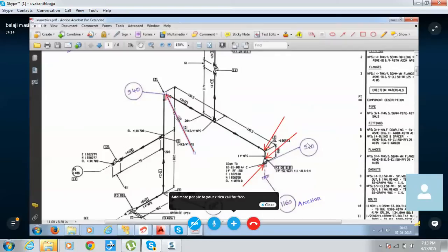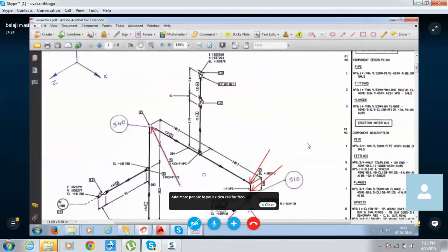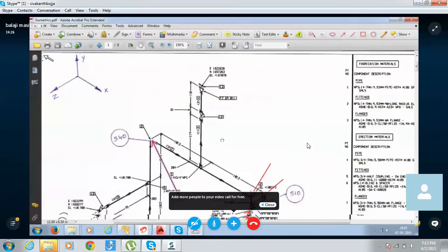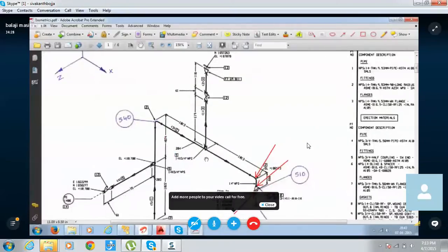Or we can directly go to this end of this elbow. If there is a connection, fixed connection. This is a small bore line, no? You see, this is 14-inch line, main line, and this branch is 3/4 inch. So that is very, very small. So no need to go. If it is a 2-inch line, we can consider. Then we should give SIP, and we have to give the T.